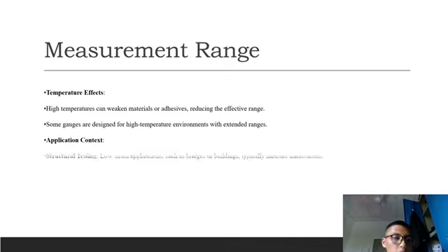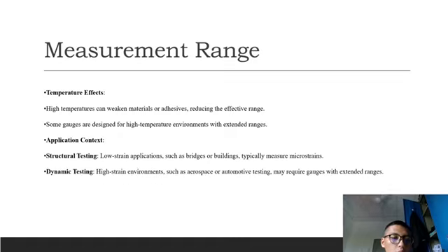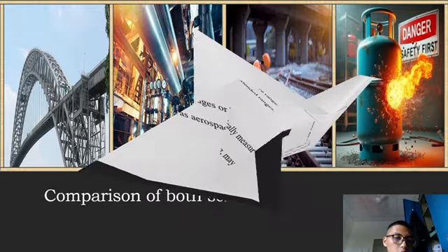For the application context, structure testing, low strain applications such as bridge or building typically measure microstrain. Dynamic testing, higher strain environment such as aerospace or automotive testing may require gauge with extended range.